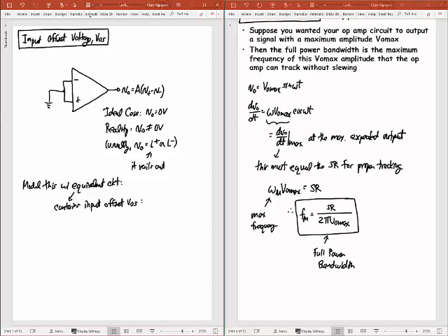So basically the op-amp is behaving as if it were just like this symbol, which is my ideal op-amp, putting out my output voltage, but instead of having just straight into the negative and plus terminals, I have some fictitious voltage source that I'm going to call VOS, that I'm going to stick right here at the plus terminal, and I'll put nothing on the minus terminal, and that now models the effect of the offset voltage.